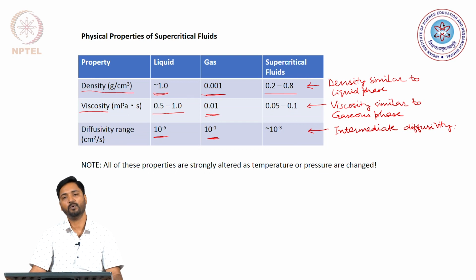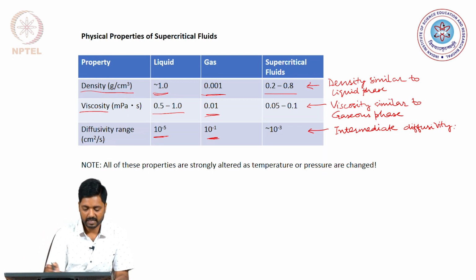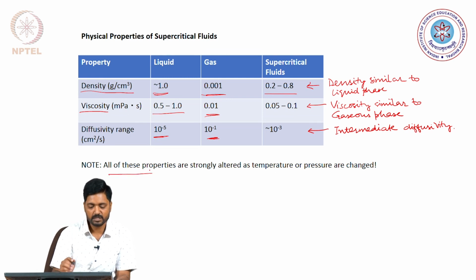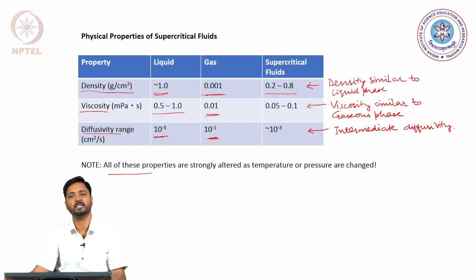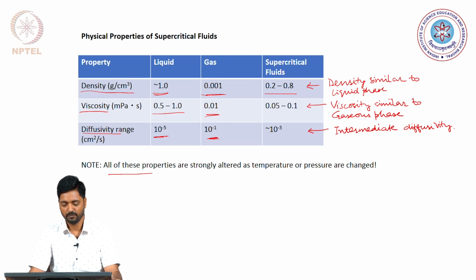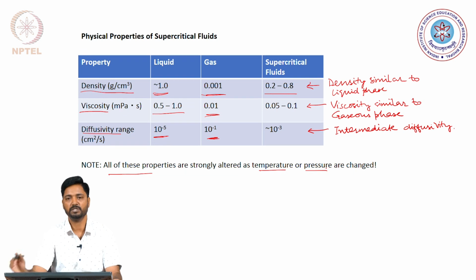So, an important point to be kept in mind here is that all of these properties, whether we are talking about the density, viscosity or the diffusivity of the supercritical fluids, are very strongly altered by change of temperature or pressure.